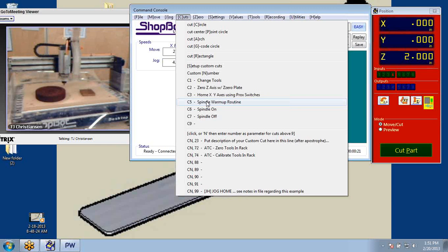What it's doing is, this is a several $1,000 spindle. It gets bigger. That is doing all the cutting for you, and the only thing that's keeping its internal parts cool is that little tiny fan up on top of it. So you're going to want to do a warm-up of the bearings before you apply a load to it. I don't want to just come in here and start augering into this piece of bamboo that I have here that's really hard without warming up my spindle, because that's how I could wreck the bearings in it.